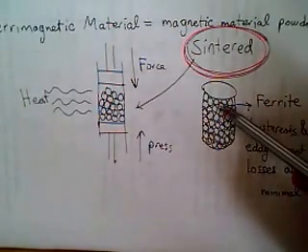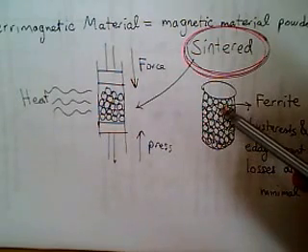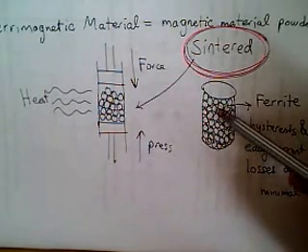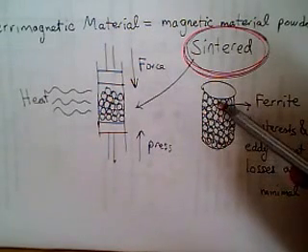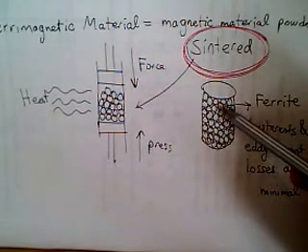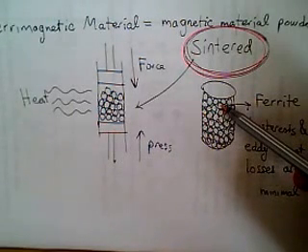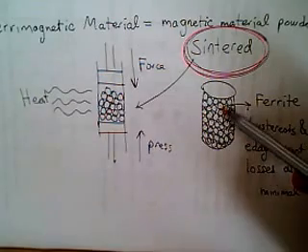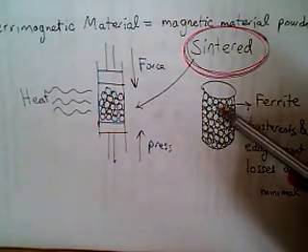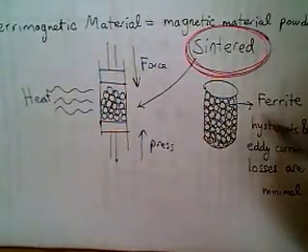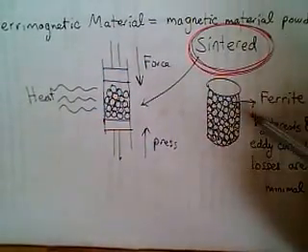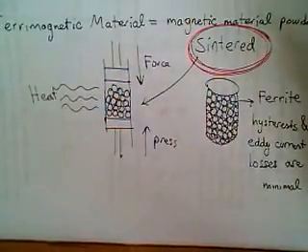And the material is encapsulated in small little powders, and in between the powders the electrical resistivity is so high, so eddy current and hysteresis currents, which can be studied in other slides, will be very limited in that volume. So hysteresis and eddy current losses are minimal, or rather eddy current losses, compared to the solid structures.